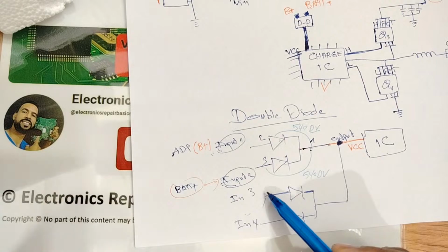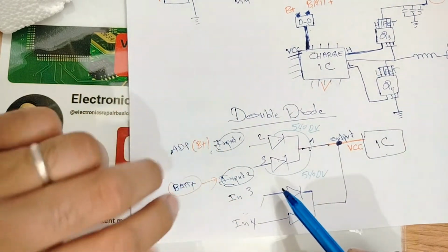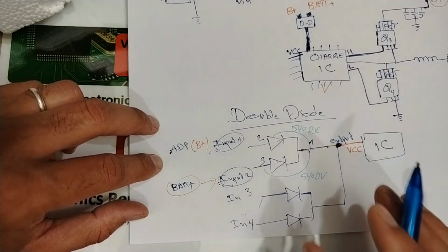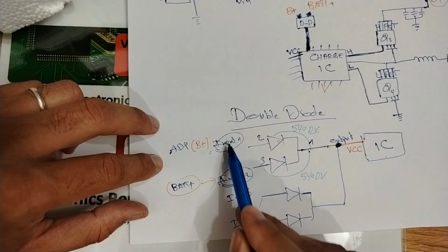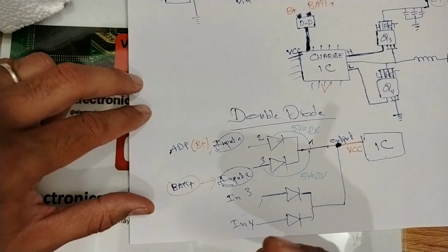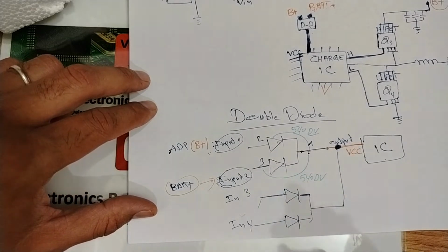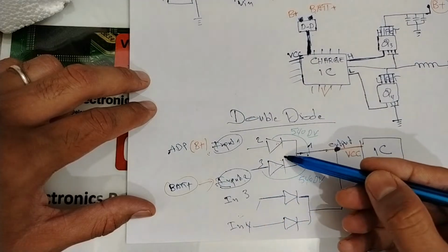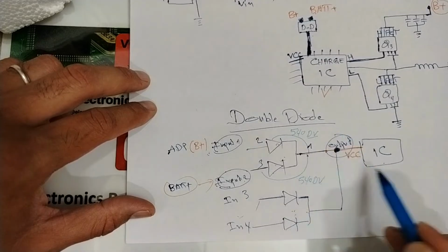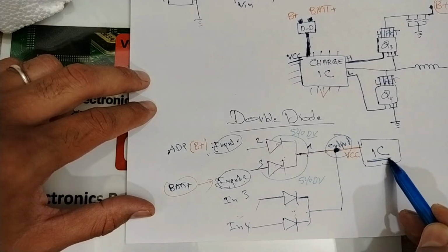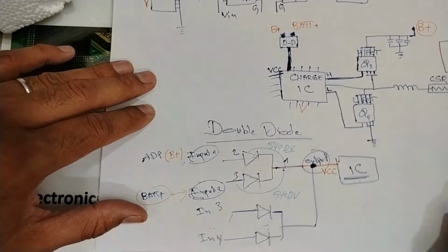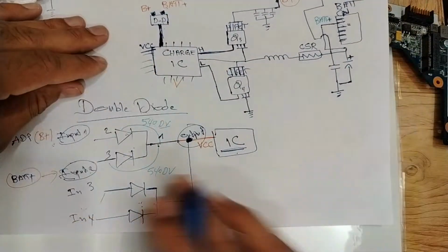Here we call it duplicated outputs. For example, we use this for safety. But in other motherboards, in enhanced and improved laptop motherboards, you can also find 2 double diodes next to each other in order to generate one output to power an IC. It could be a charge IC, a CPU IC, a RAM IC, etc. But my friends, for the MOSFET, it's different.